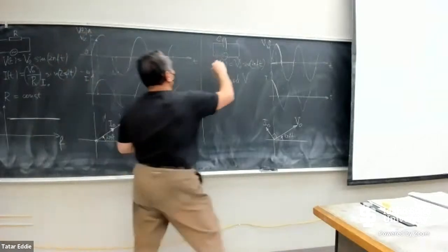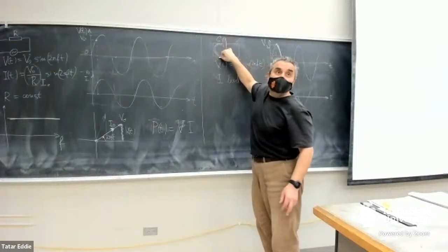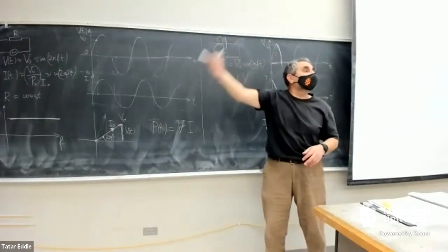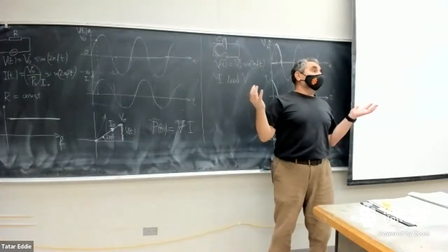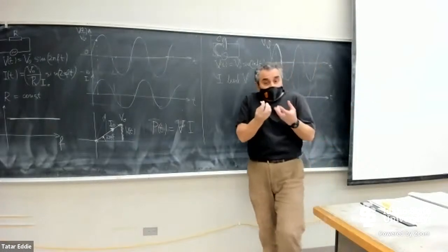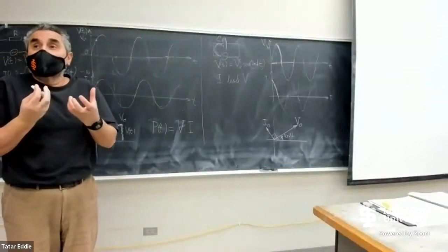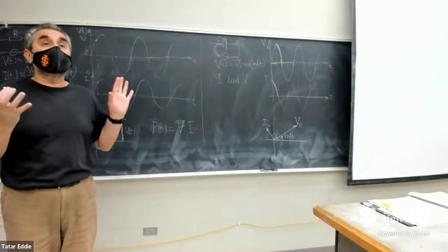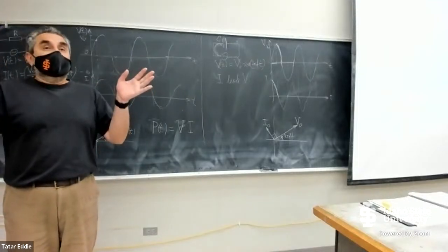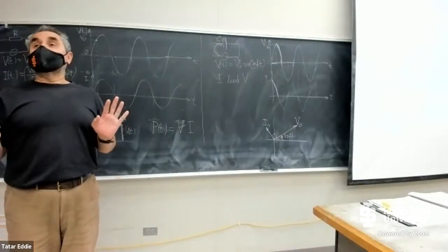So the capacitor stops signals that have 0 frequency, but the capacitor easily allows higher frequency signals, because higher frequency means, well, you charge, discharge, you charge, discharge. So constantly the AC current is going to be moving if you have AC voltage. So the capacitor has this interesting property. It resists signals that have 0 frequency or low frequency, and allows perfectly well high frequency.